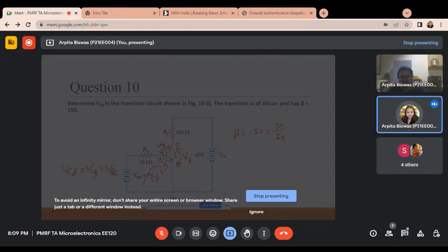No. This is not the right way to solve this. Just see the equation. Here nothing is given. It means this is the emitter, no? So this is the base to emitter junction, so here VBE is also present. Okay, it is not written, but it is present, and the value of VBE in common emitter is 0.7 volt. So then try to solve.